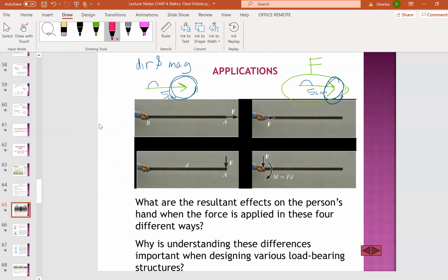Just pay attention. Look at this. So we have this force here acting at the edge there. So I'm going to shift this parallelly. I'm maintaining the distance, the magnitude, and the direction. So when you shift from an end here to here, you don't imply anything. It can be freely moved. That's it. So you're going to have the same thing whether the force is at the edge there or down here. Can you see this one and this one?